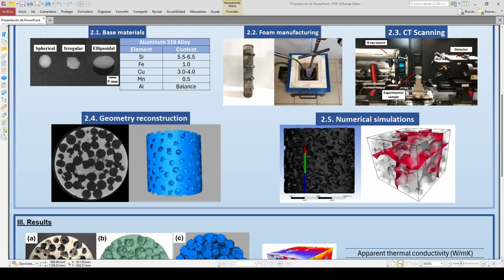For the case of mechanical simulations, we use ANSYS Mechanical in its version 19, and we configure the boundary conditions to simulate an isostatic compressive test. This means that we use a displacement in one of the circular faces and a movement restriction in the opposite one using a fixed support boundary condition. From these simulations, we obtain displacement and force data to calculate the elastic modulus.